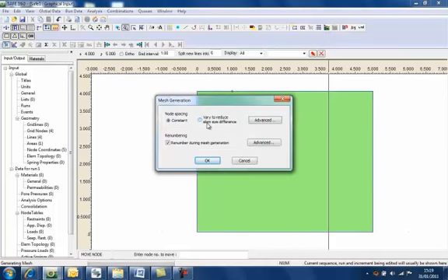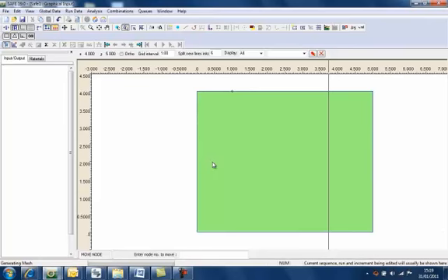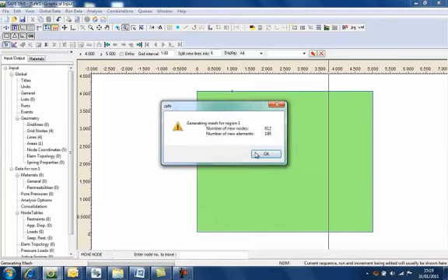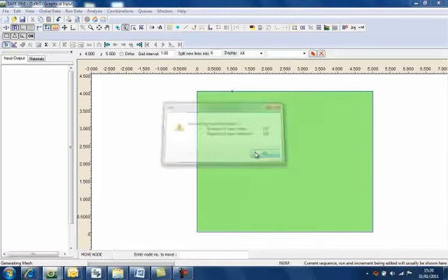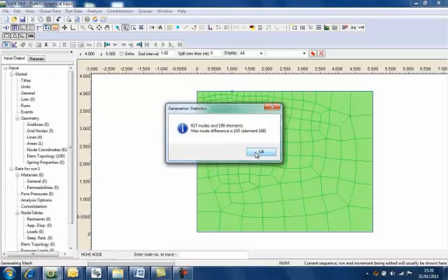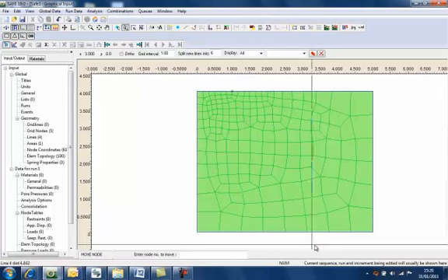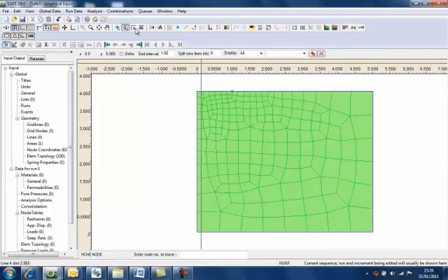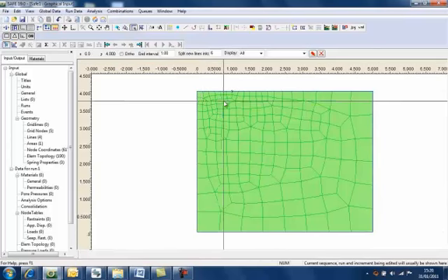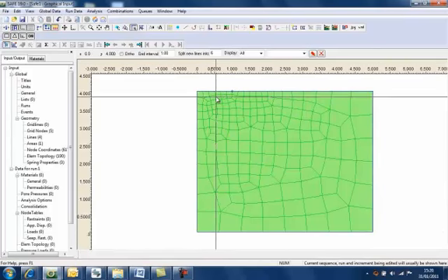Now, in this specific case, you can choose constant mesh, but SAFE enables us to vary the mesh to reduce the element size difference. Anyone who does finite element analysis will know that the meshing process is very important for the accuracy of the results, and this will increase the accuracy of the results. And as you can see, the elements are actually concentrated around the node. So that will help us, for example, if we were going to apply a load at that point.